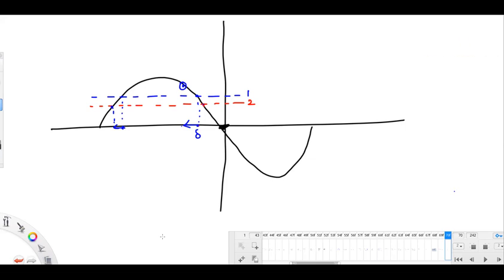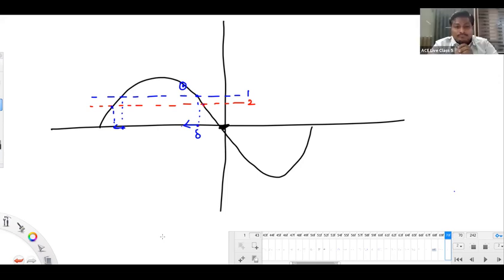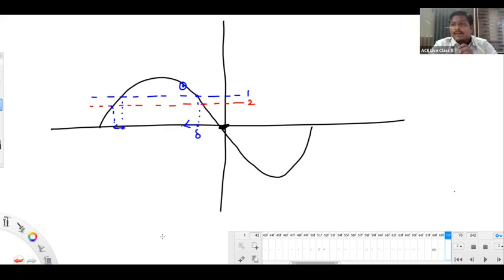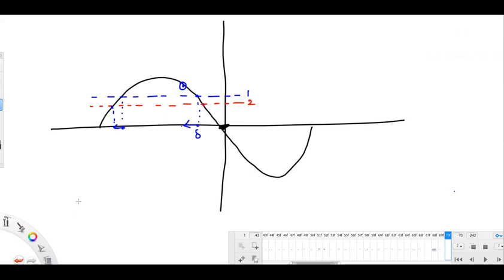So leakage current, which is a conduction current, we have neglected. Sir, will the capacitor current flow between conductor to ground or between conductors? Conductor to ground, conductor to conductor, any conducting body to another conducting body, if there's a potential gap.